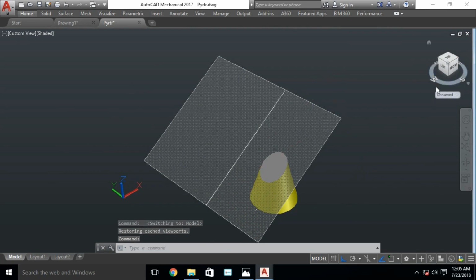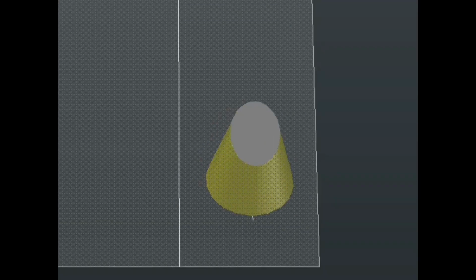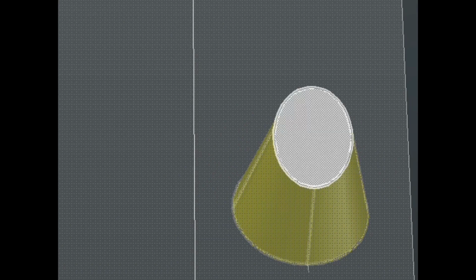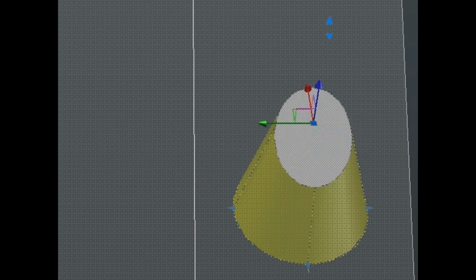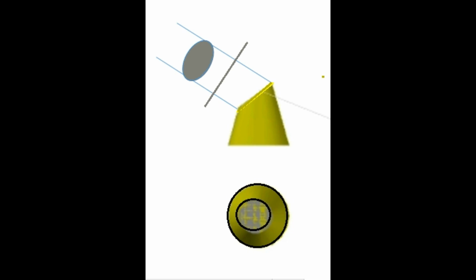As you can see, from the direction perpendicular to the cutting plane, this ellipse, this cut portion which is now visible on your screen, is going to be our auxiliary view or true shape. Now we will draw this in this manner. This is going to be our final front view, top view and auxiliary view.